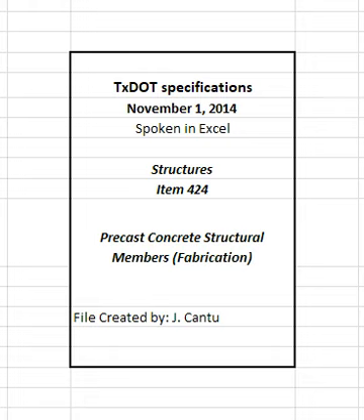4.1.1 Shop drawings. Prepare and electronically submit shop drawings before fabrication as documented in the Guide to Electronic Shop Drawing Submittal available on the Bridge Division website. Provide one complete approved 11 x 17 inch set in hard copy to the department inspector at the fabrication plant. Stamp it for Construction Division Inspector. The engineer may require additional complete hard copy sets.